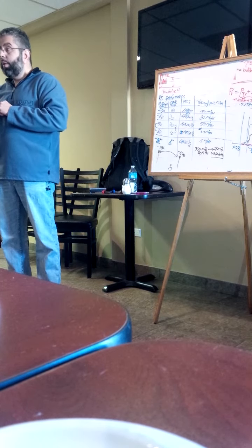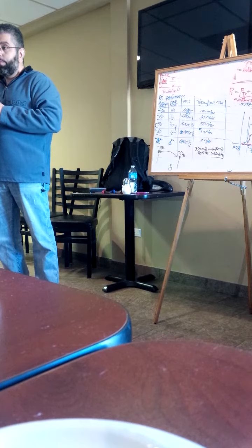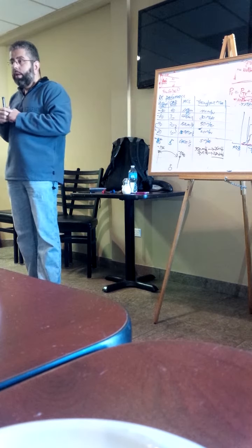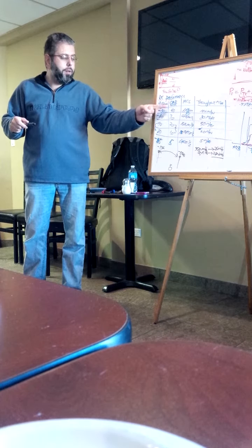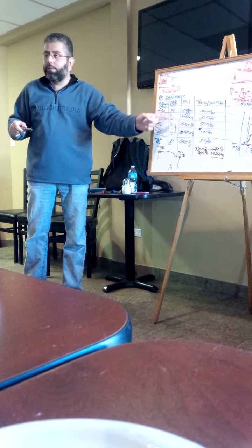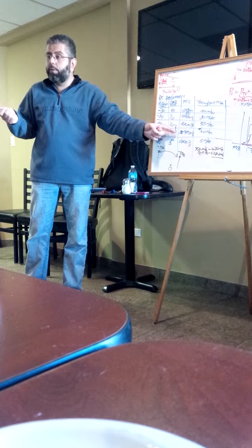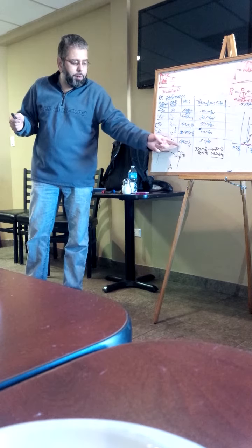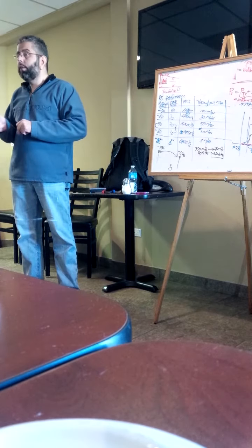Again, if I hear nothing, it depends on how much time I have. If I know I have 5 minutes, I've got a long time to figure this out. I'll try and acknowledge it. If it comes back and still nothing, I can decide to do another thing. I can decide to drop my MCS because maybe there's interference. Maybe it's an interference problem, so I can drop it and say, I'm not looking for a lot of data. Let me go to the lowest throughput rate. I'll go to QPSK half, and I'll send it at QPSK half.